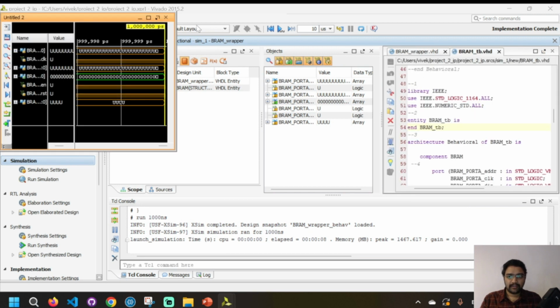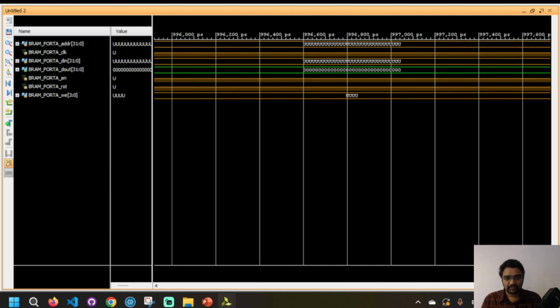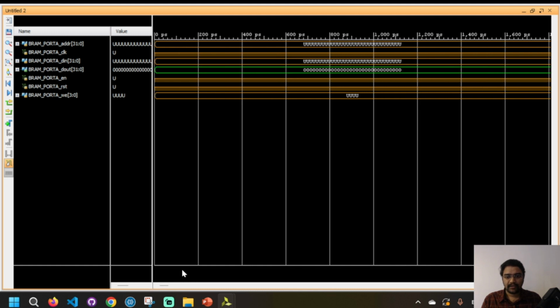Now get down this part and open this part. You need to click control. Some of you have asked why it is showing universal. It is the infinite part. Timing has gone to 1 lakh picoseconds, 10 lakh picoseconds. Again, you need to click control and scroll down, or you can click on this navigation bar and come back to the starting point, and you can see some variations. And now again, if you want to zoom out, click control and scroll down, scroll back.